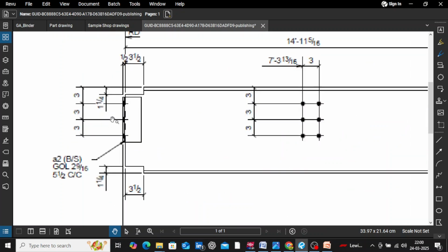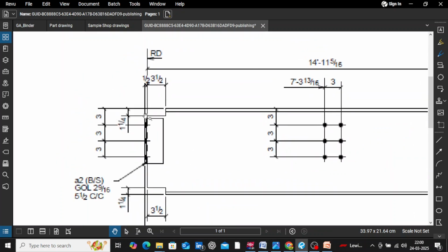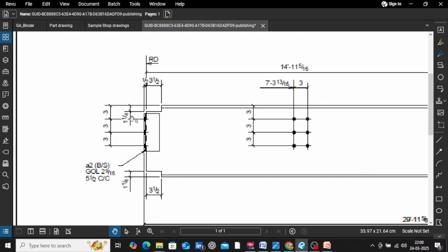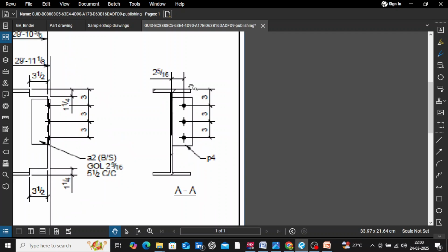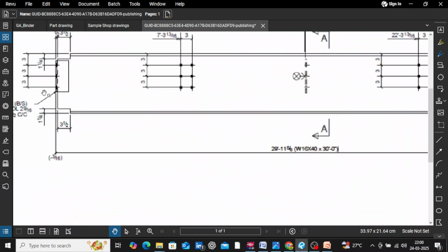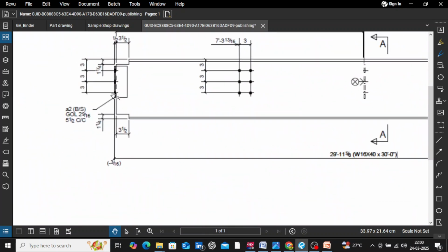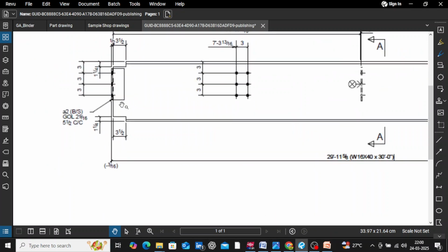Now all these secondary parts will be connected with reference to the left extreme end of the main part in X direction, in Y direction and in Z direction. Once all these are fixed in all the 3 directions, we'll make sure these will be fit up to the main part using welding or bolting.